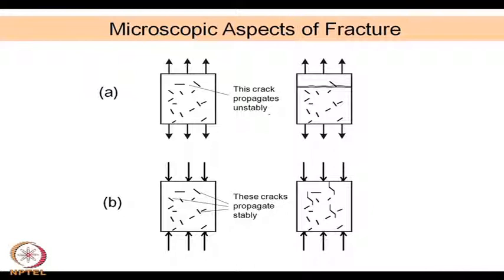Generally, ceramics are less thermally conductive, so temperature uniformity is a problem in all ceramic preparations. Ceramics always require high temperature for sintering and other fabrication processes. During cooling, if it is not an equilibrium cooling, there will always be thermal stress generated in the sample, and those thermal stresses may lead to different kinds of cracks. These cracks are pre-existing in most samples.